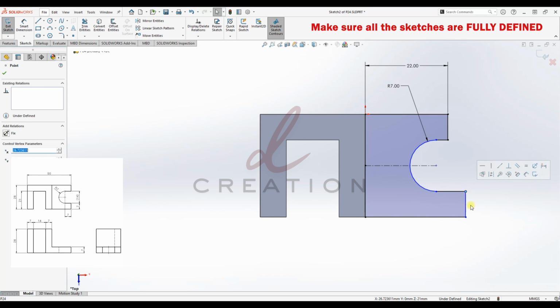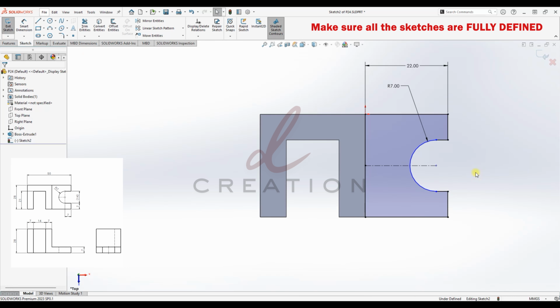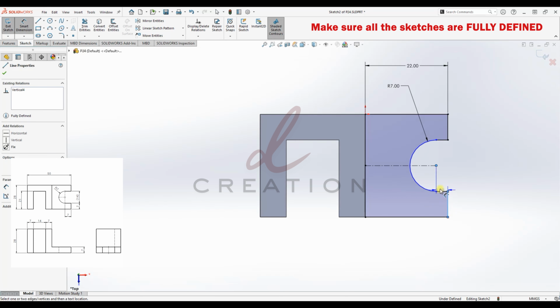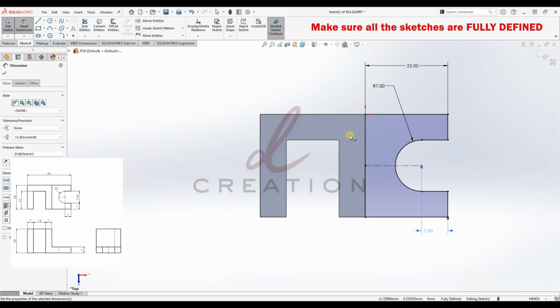And then make sure this line and this line are vertically related. Click on the point, Control, click on this point and add the vertical relation. And now finally we are going to add the length of this one, which is 7. Alright, so our sketch is fully defined.